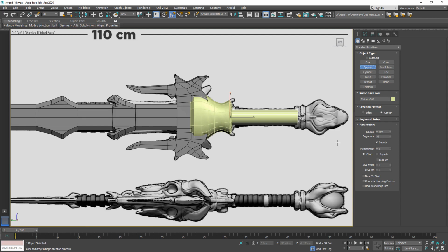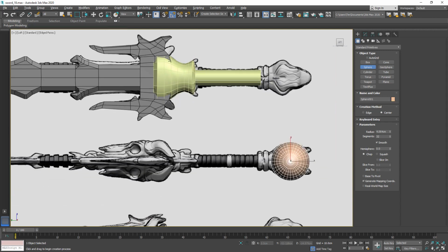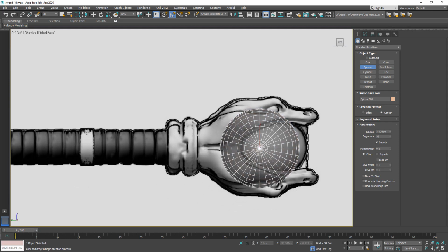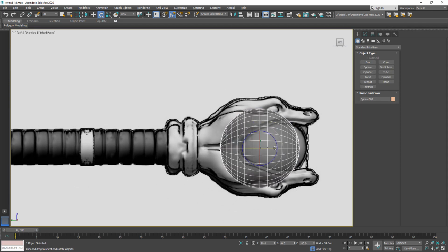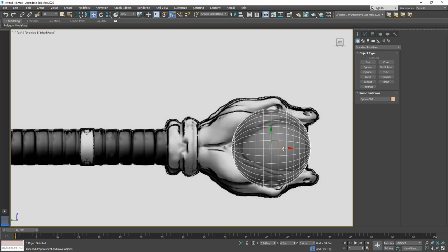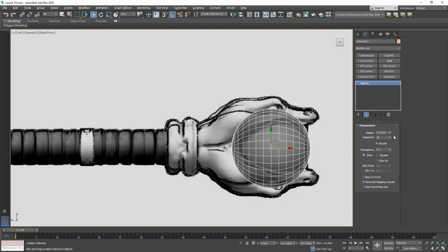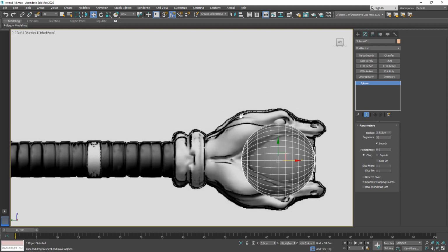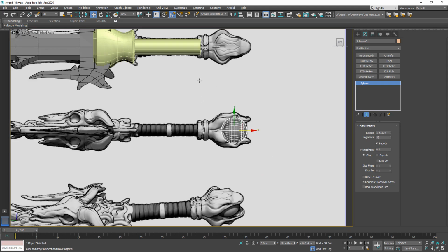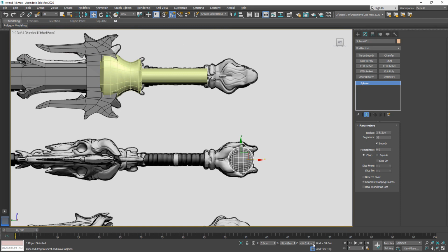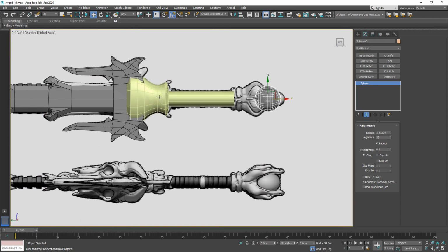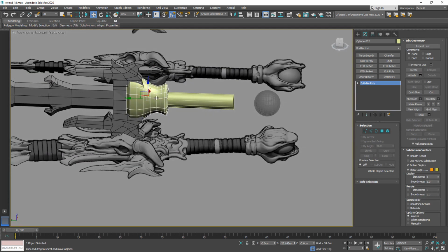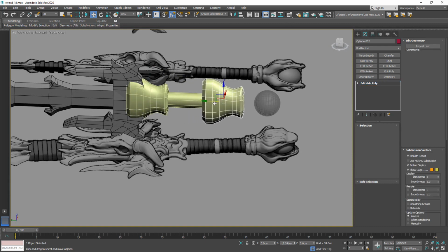Next, let's go here to our left orthographic view and let's create a sphere. I'm going to have 32 sides on it, and let's go here to rotate and give it a 90-degree rotation here. Position it so that it actually fits there on the reference, and I want to scale it down a bit. And now we actually want it to be up there, so we're just going to press 0 here on the z-axis, which automatically brings it up.